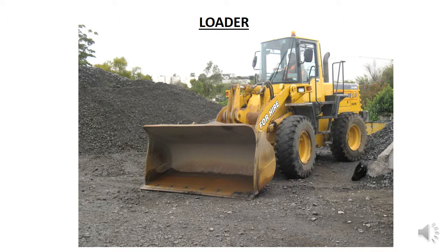Loaders consist of a wheeled body with a bucket in the front. The bucket is mounted differently from an excavator, so loaders tip up when loading, while excavators tip down. Tipping up when loading allows them to better load loose materials, and having a larger bucket means they can load more than a similar sized excavator. Being mounted on wheels allows them to move faster, and they are often articulated so they can turn tighter. These features enable loaders to load trucks faster than other plant.